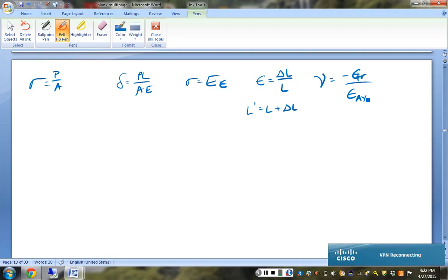It gets shorter by 1/3 of an inch this way. So you know that the ratio has to set up with the axial being the bigger number, and for metals it's usually very roughly 1/3. So the transverse shrinks about 1/3 what the axial grows. Use your common sense. What else do we need to know out of part 1? That pretty much covers part 1.